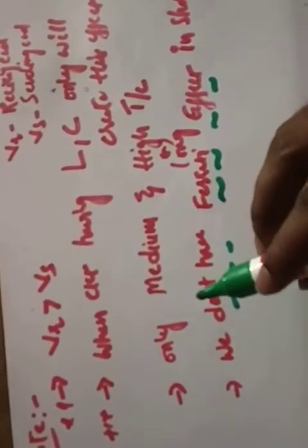Right? So this is a very important statement. Short transmission line, medium and long transmission line, L and C. Right? And another one: on what conditions will they ask, on what conditions this receiving end voltage is greater than the sending end voltage? You will know the condition: no load condition,